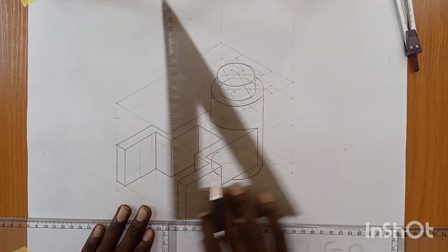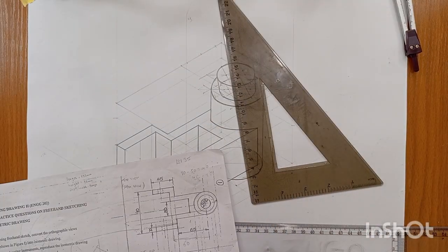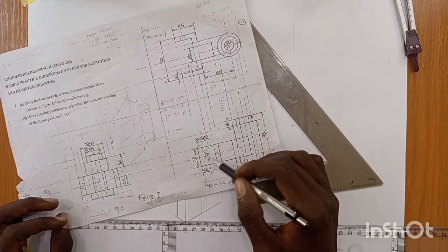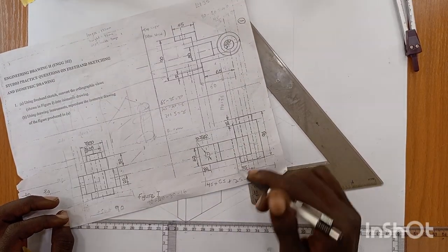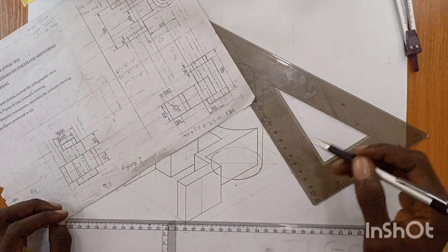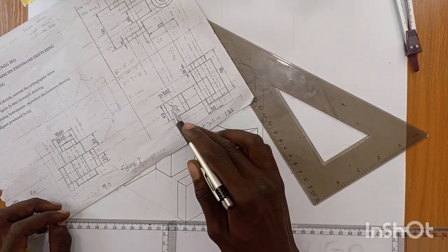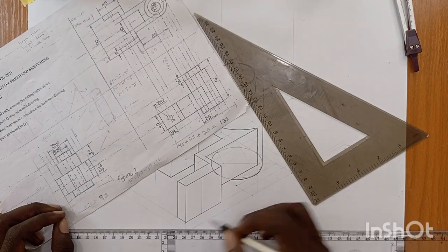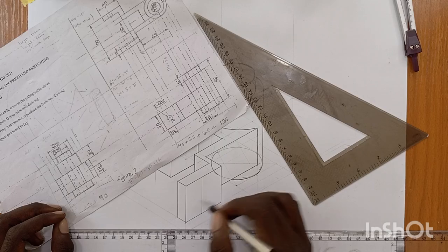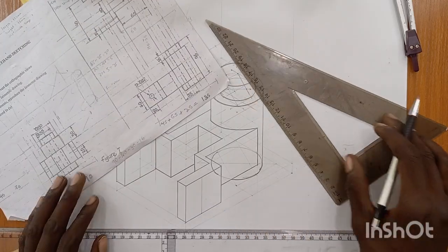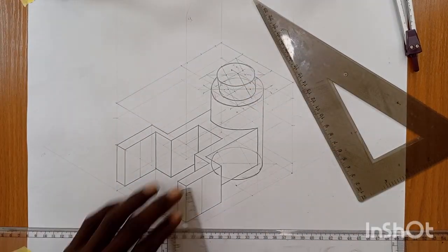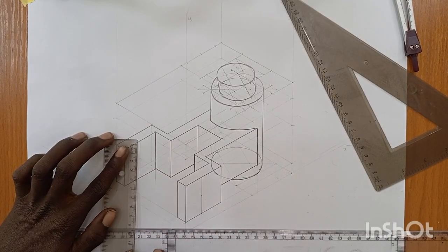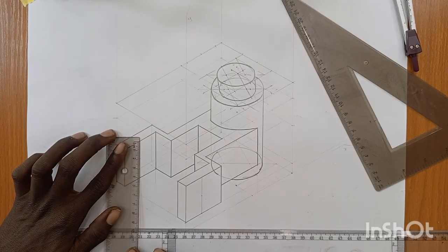Take it up. So now the next thing to do is, as you can see, the diameter of this small hole is given as what? 12. Therefore the radius will be 6. So now what are we going to do now? I'm going to have to draw a square at the center here. So now from here, the height of this is 40, and from here to here is 20. So when we divide this into 2, we take our 20, we have our center line. So let's divide this into 2. We are going to measure 20 from the top line. From above here, we measure 20.